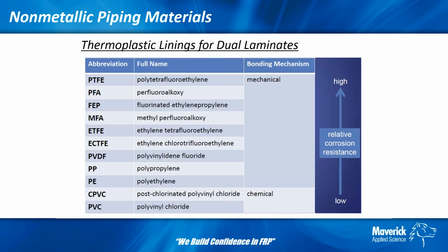And roughly, if you're looking at PVC to CPVC, we're talking, say, $8 a lineal foot or something like that for a lining, where you get up to PVDF might be $25, $30, and then you go up to FEP, maybe you're approaching $50. That's just a general ballpark of order of magnitude and the differences. But they all have their place.